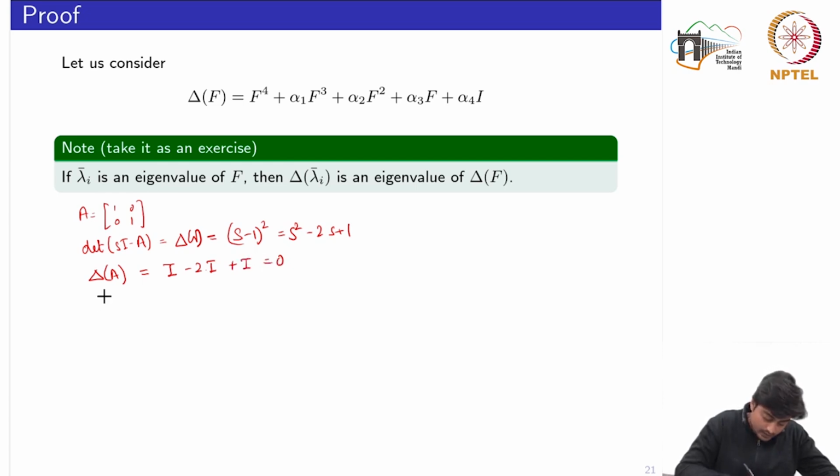So now define another matrix. Let's say we want to place the eigenvalues of the closed loop matrix at, let's say, -1 and -2. So I form another matrix.